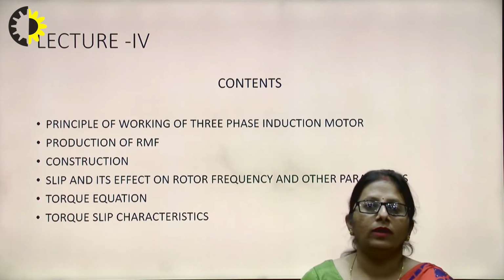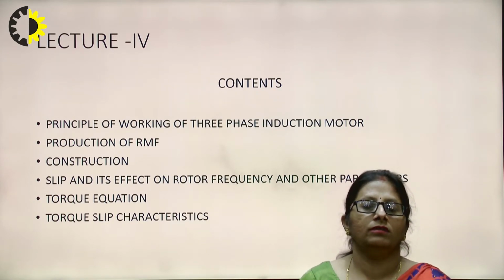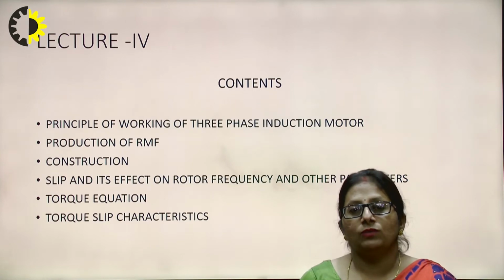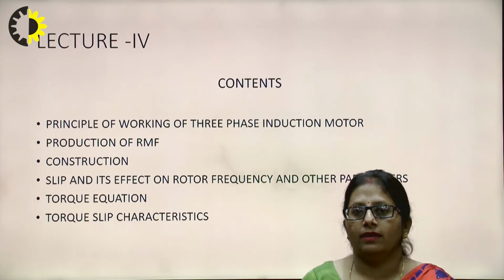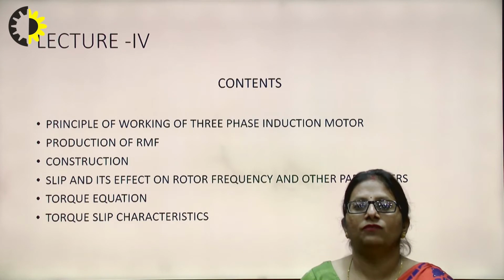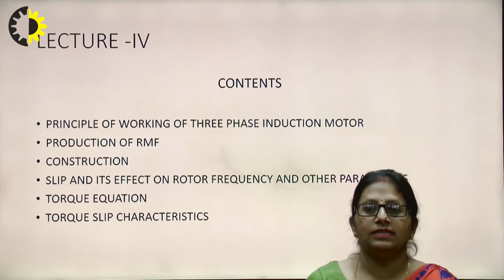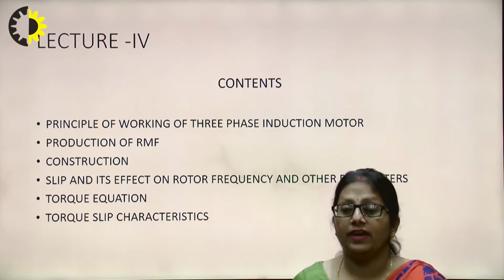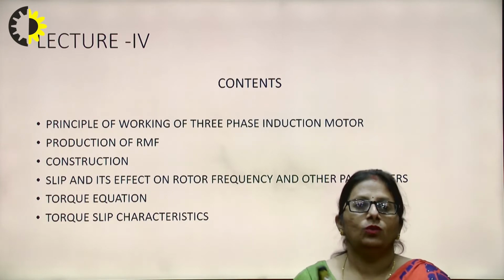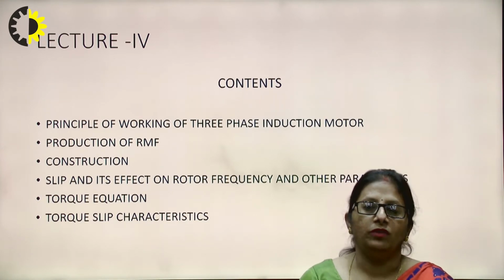So it holds good in applications where you require the starting torque to be high. Likewise, the pulling or lifting jobs, such as elevators, lifts, hoists, cranes. These kinds of applications are found for DC series motors.